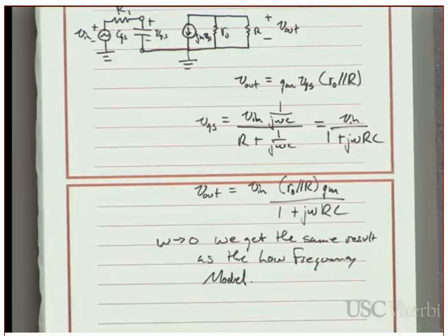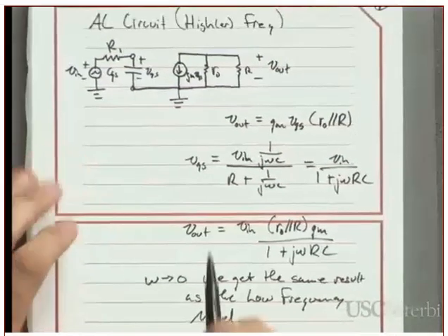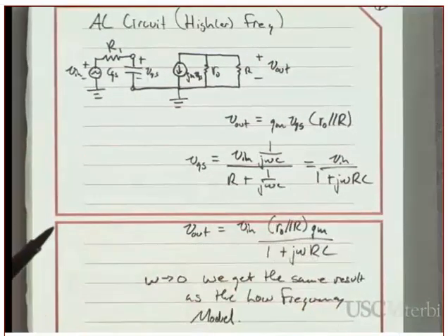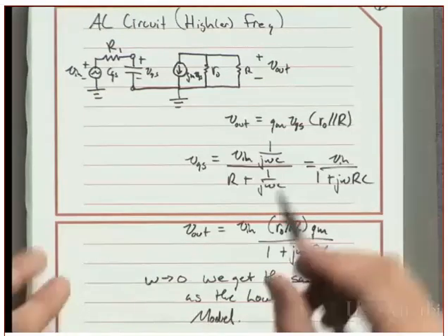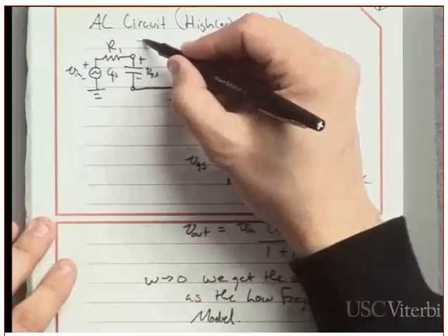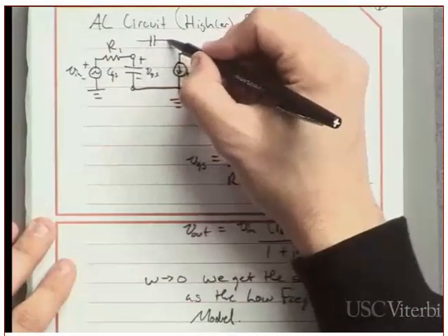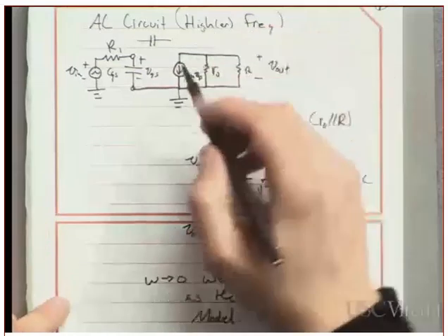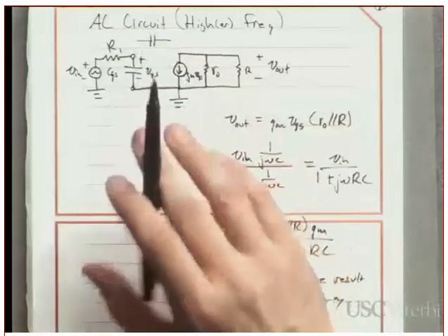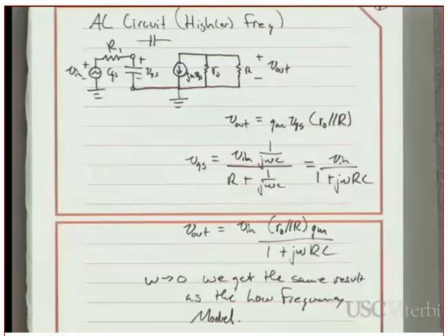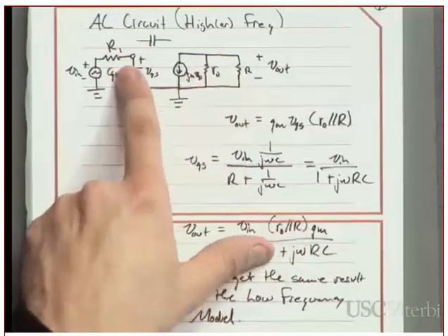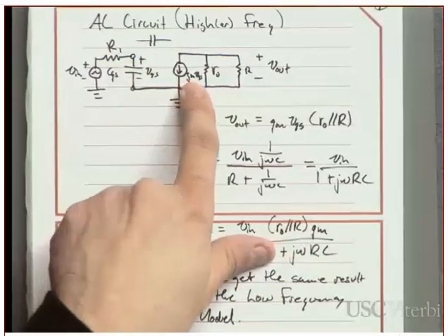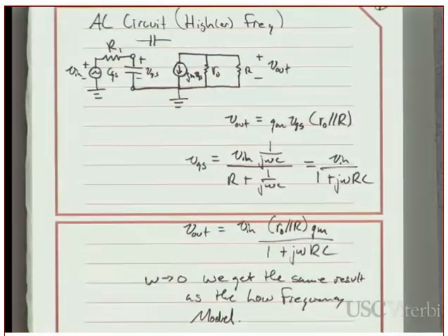So when you're looking at circuits in this course, usually this model will be good enough, unless you find out that your gate to drain capacitance is an actual issue, in which case you'll have the capacitance from the gate to the drain up here, and you'll have to consider that in calculating everything, because now that complicates everything a lot more, right? Because now the current going through this guy is partially coming from here and partially coming from here. VGS now also depends on GM VGS. So there's a lot more feedback that actually occurs.